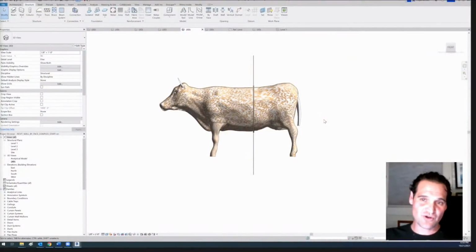There are just some things you need to be aware of because you're modeling using the massing environment in Revit, which can be a little touchy because it uses Hermite spline formulations, not NURBS. The important part is that as you sweep through profiles, you need to make sure they're continuous and smooth. You can't have anything that's really wonky. So my profiles for this cow from the back leg all the way to the nose would look like this. If you see my cursor, it'd be radial lines from here to about here. Then they'd be parallel lines to here. And then as I hit the neck, they would be radial lines again to here. And that's how that profile would look.